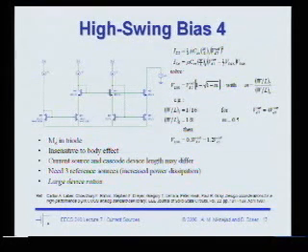Okay. Any other reasons why I might not want to just have one bias generator and use it all over the place? It's kind of a more general question. Used to be IR drop. That's right. IR drop is another issue we'll talk about. Takes parasitics, right? You have to route voltages around, and if currents are flowing through, then you have an issue. But what about just routing a voltage, right, with zero current? If I'm just taking this voltage, right, there's no current going into my cascode device, so there's no current. So then the resistance doesn't matter.